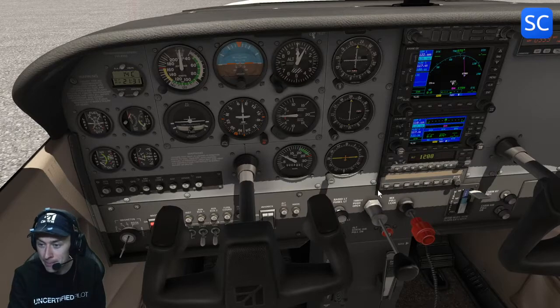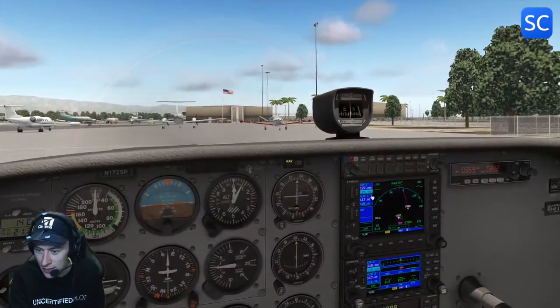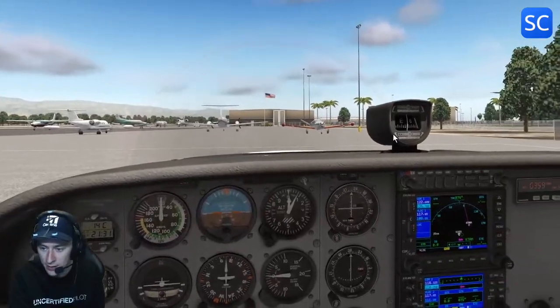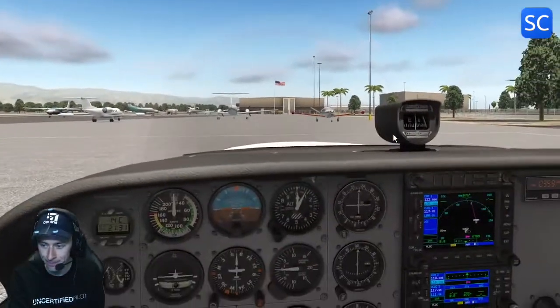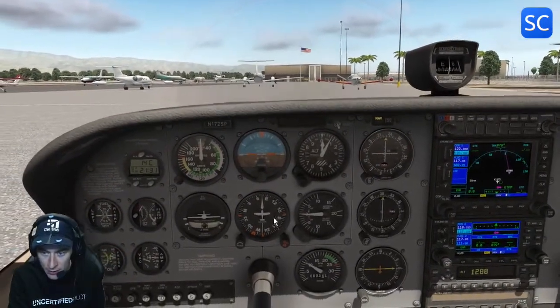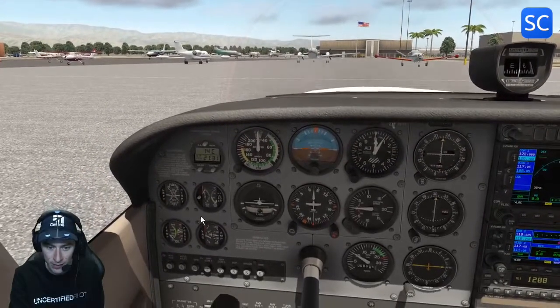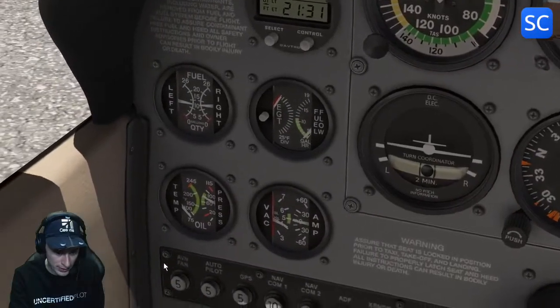Okay, now we can set some frequencies. We're just going to do a traffic pattern here. So we only need, oh sorry guys, only need a CTAF frequency 122.8. That's set, that's good. We're not going to listen to ATIS. That's just fine for today. We got perfect flying weather. Yes, again, no annunciated messages. That's good. Airport elevation, all that stuff we already set, and it's still set. Everything is stable. Fuel's still there, and engine oil temperature is slowly increasing.